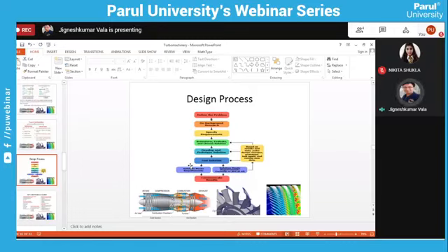So starting with the axial fan. The axial fan has a huge diameter, and it has a very high number of blades. Then after the air is sucked from the atmosphere, some process is going on, and using the axial flow compressor, using a number of stages, we can raise the pressure and minimize the velocity. There are different types of axial flow compressor stages: the low pressure compressor, the high pressure compressor, and then after that the combustion part is there, right?